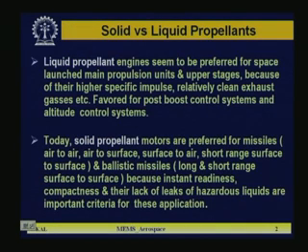Now, if you compare liquid versus solid propellant, we can summarize like this. Liquid propellant engines seem to be preferred for space launched main propulsion units and upper stages because of their higher specific impulse, relatively clean exhaust gases, etc. They are favored for post boost control systems and altitude control systems. Those are the plus points of liquid propellants.